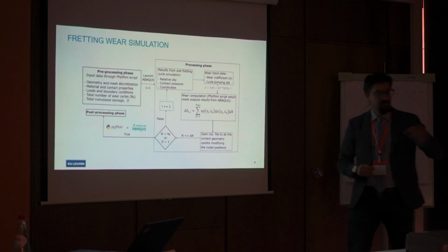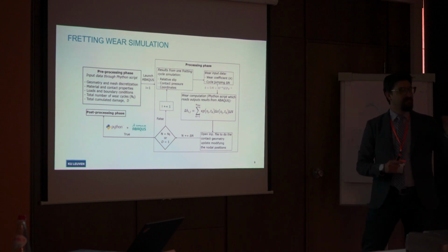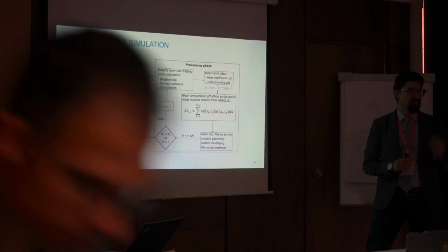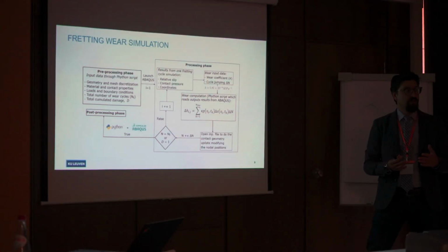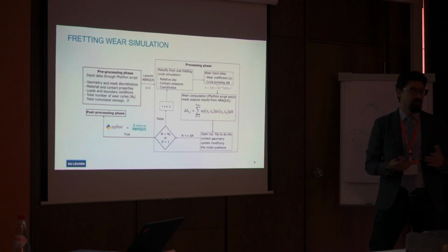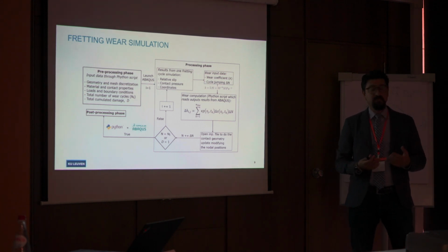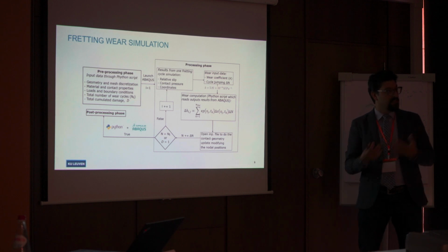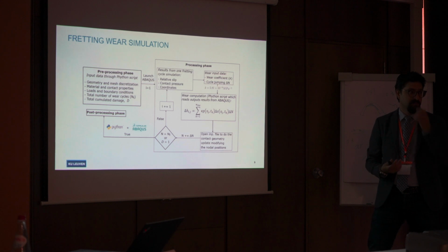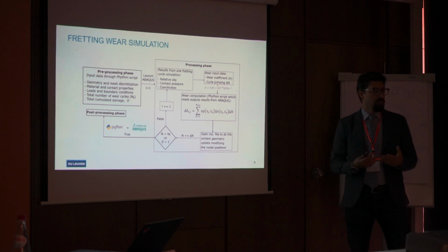It's good that you brought it up. I'm not suggesting that you have to take wear into account, because maybe it doesn't have that much effect, but it has an effect. The idea was that wear could postpone crack initiation under the partial slip regime, but in this study we showed that it has a minor effect. It has an effect, so it's not that it has none. But is it worth spending time to simulate that for partial slip? It depends on the application and on what you want to use the model for.